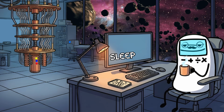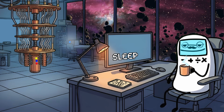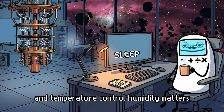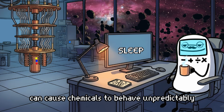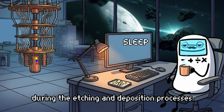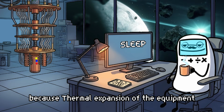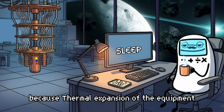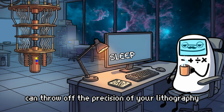The clean room also needs very careful humidity and temperature control. Humidity matters because water vapor can cause chemicals to behave unpredictably during the etching and deposition processes. Temperature matters because thermal expansion of the equipment can throw off the precision of your lithography.